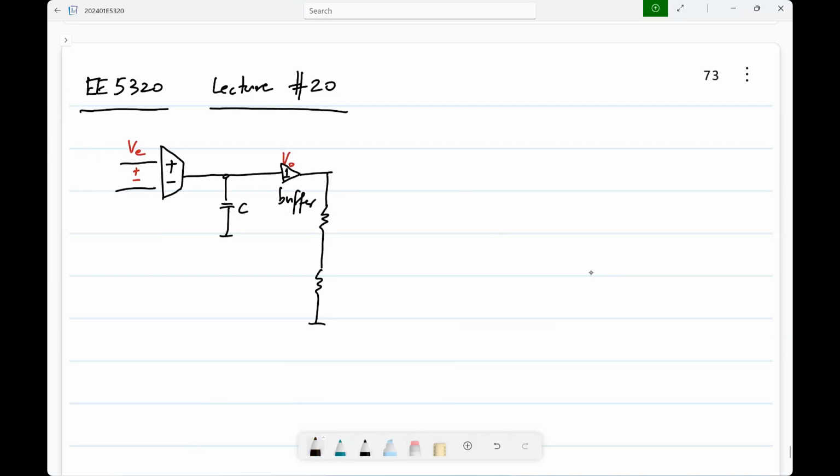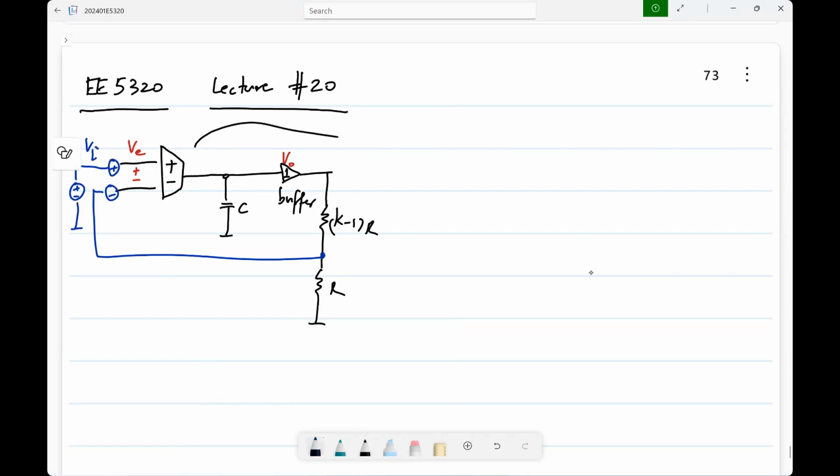Then you can make an amplifier using this, the negative feedback amplifier. This is the negative terminal of the op-amp, this is the positive terminal, and to which you connect your input voltage. Okay. So we will go into the implementation details, but the basic implementation of this would be a differential pair with a current mirror load. It has a differential input and a single-ended output.